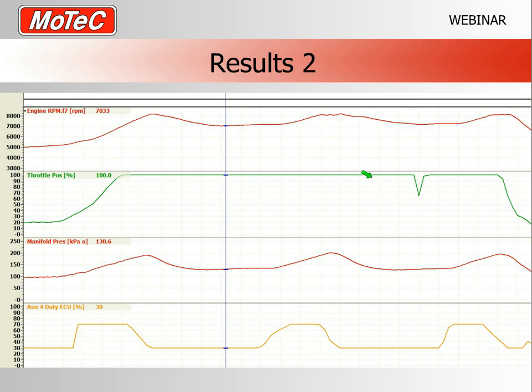And it's at this point you can actually notice in reality just how slow the boost does change. So here the duty cycle went up to 70, and look, it's taken all this time here. We'd need to know exactly what that is on the time scale down the bottom, but maybe nearly a second for that to respond.